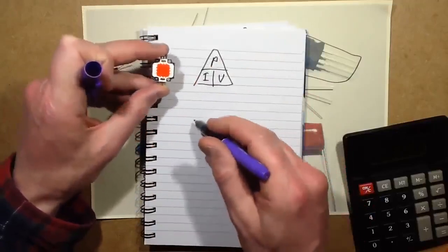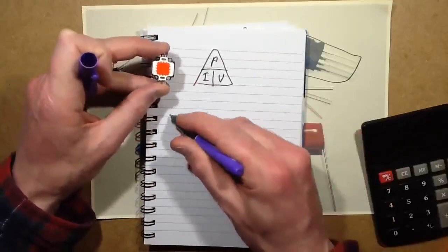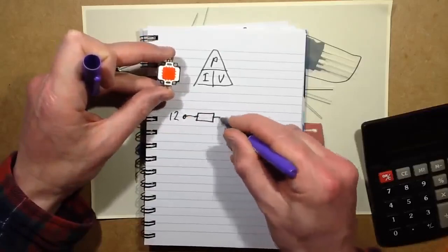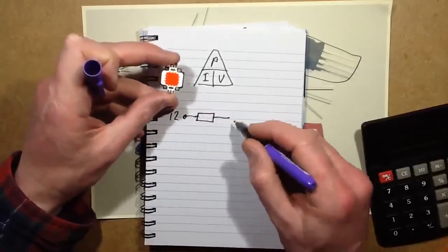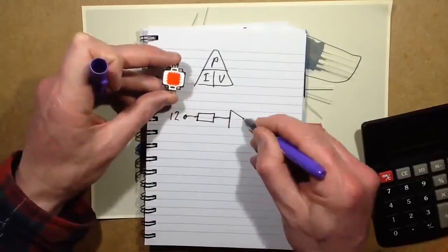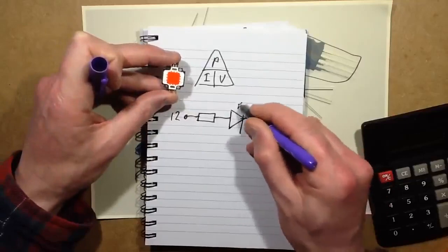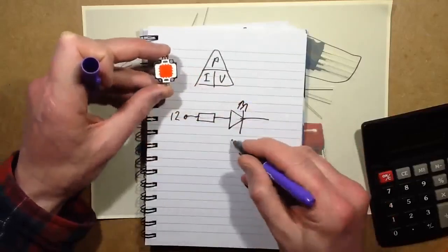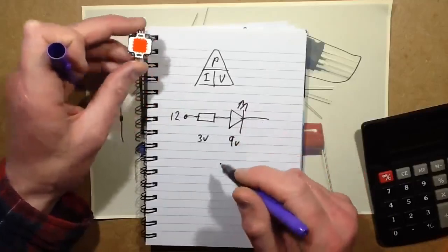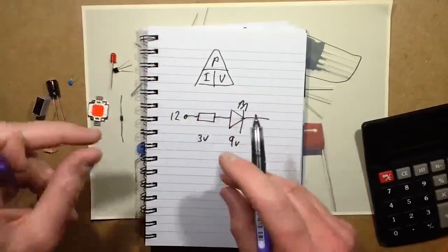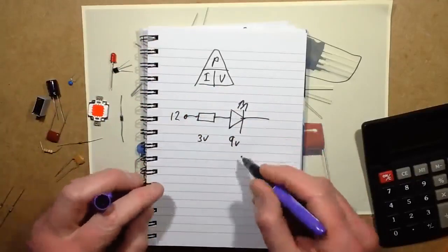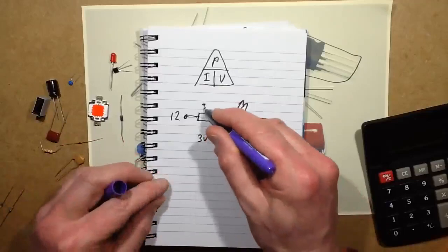So to calculate, if we were to actually put a resistor at 12 volt supply again, and choose a resistor to limit the current through this to the 1 amp. So let's see, I'll just draw it as a huge big LED. I'm not going to draw what's in it. There's a 3 by 3 array. But the voltage across that is about 9 volts. So we've got 3 volts to drop across the resistor. And if we go back to the original formula, R equals V over I, we've got 3 volts divided by the 1 amp we need, so that's going to be about 3 ohms.